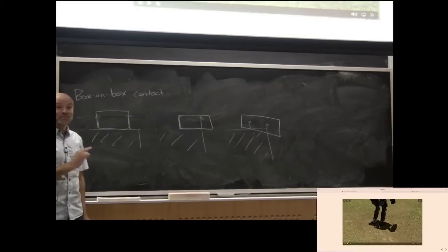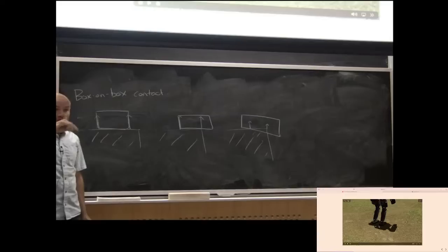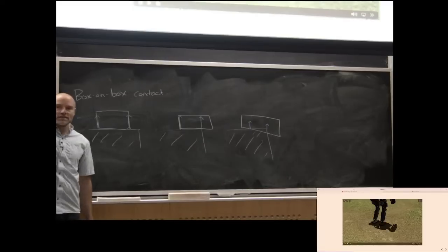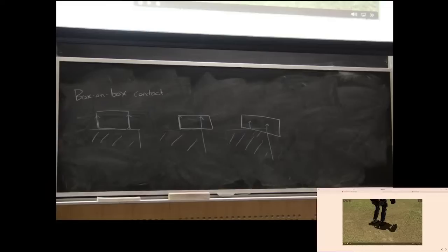And this is another big reason why simulators of contact become unstable. You'll be simulating along, you'll take steps of the integration, and it will quickly change its mind about where the forces should be applied, and then all of a sudden something will explode. Okay? That could be what was happening here too, was that it could be slightly changing its mind about where the forces should be applied.